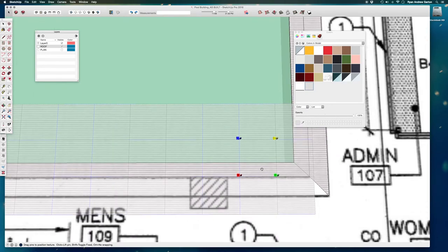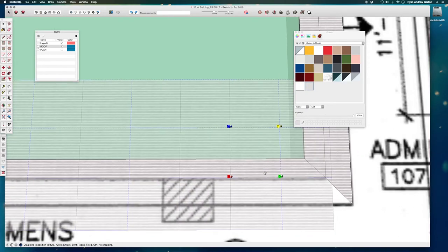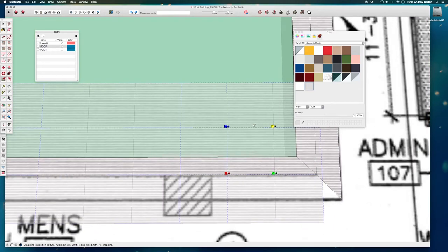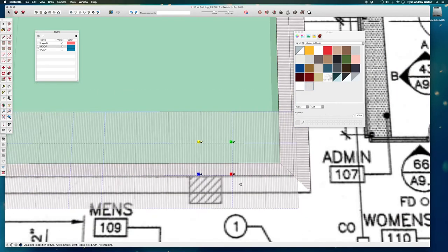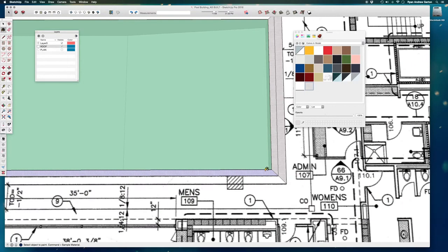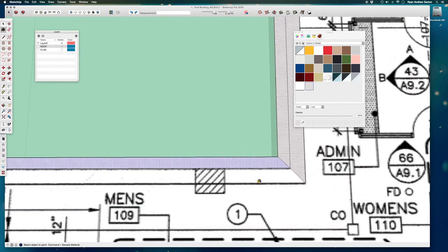I think we discussed this briefly in the beginning SketchUp class, but here we're going to get really into it. There are 4 different options for what you can do within one face when you're editing a texture. For now, I'm not going to worry about those as much as I am just going to rotate it. So again, first thing I do is click on Texture Position, right click, and now I right click again, and I'm going to select Rotate 90. And that's just going to rotate that texture just on this face 90 degrees. Done. If I right click, then I can say done.